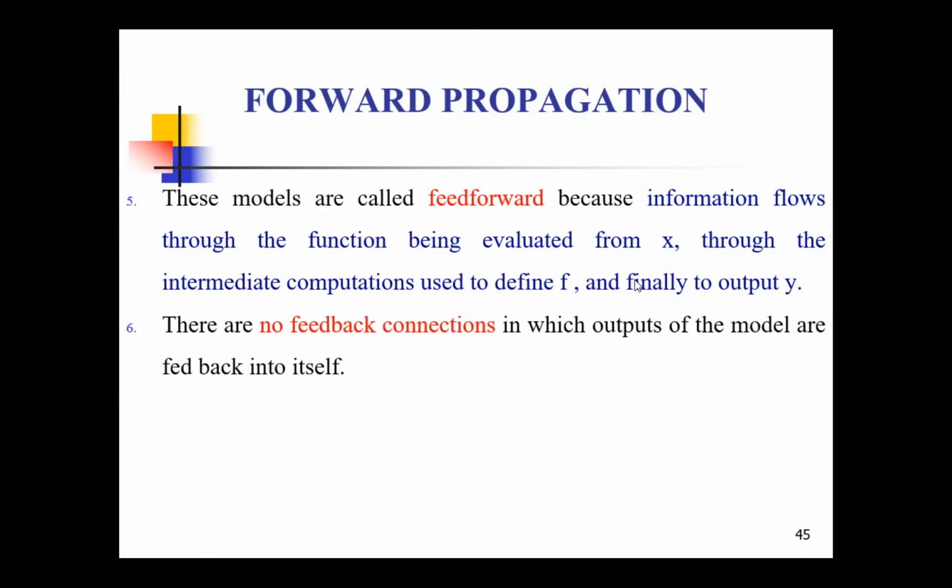If I feed back the outputs, then the system itself will adjust so that a desired output can be obtained. For example, take an air conditioned room. I set my temperature as 22 degrees centigrade. The compressor runs until 22 degrees is reached, then it switches off.